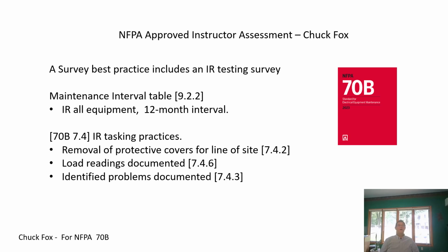Today, however, we can also take a look at Chapter 7.4 of 70B, which talks about infrared protocol or tasking practices. These would include the removal of protective covers so the infrared camera has a clean line of sight, the documenting of load readings, and the identification of any particular problems identified with heat signatures based upon the survey and scans of the electrical equipment. There have been various aspects of that done over the years.